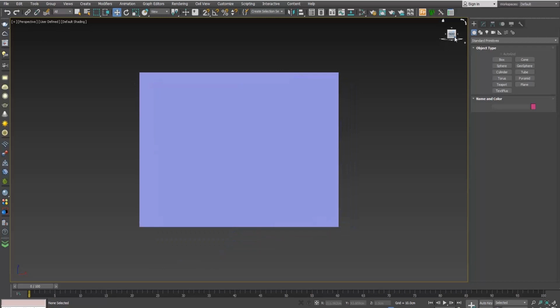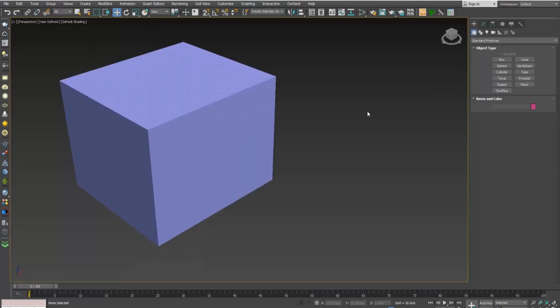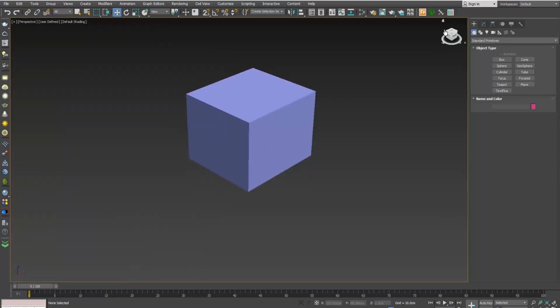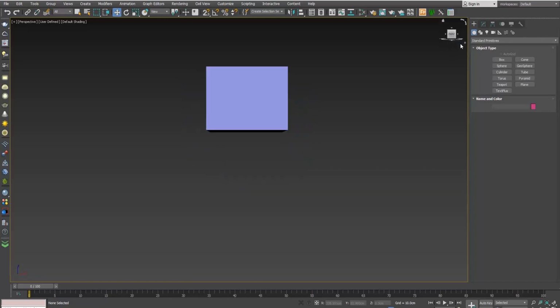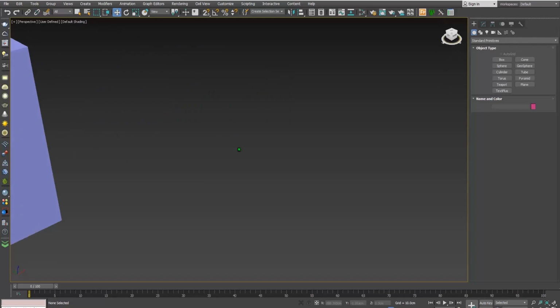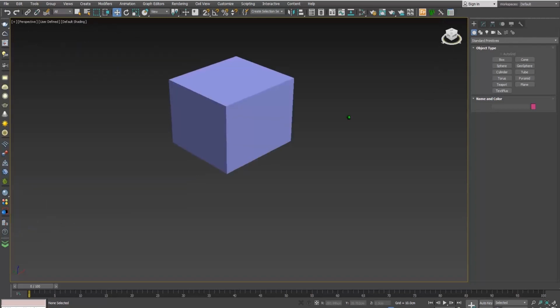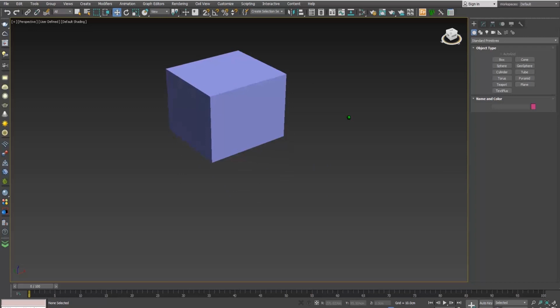When we click on front, we don't switch to a front viewport. If you check here, it still says perspective. The scene rotates to a frontal perspective. If we click on the home button, we return to the original perspective view. At the bottom of this box, we see a circle with the 4 points of the horizon. So, if I click on south, I switch to a frontal perspective. If I click on the circle and hold the cursor, when I drag, then we rotate the perspective.